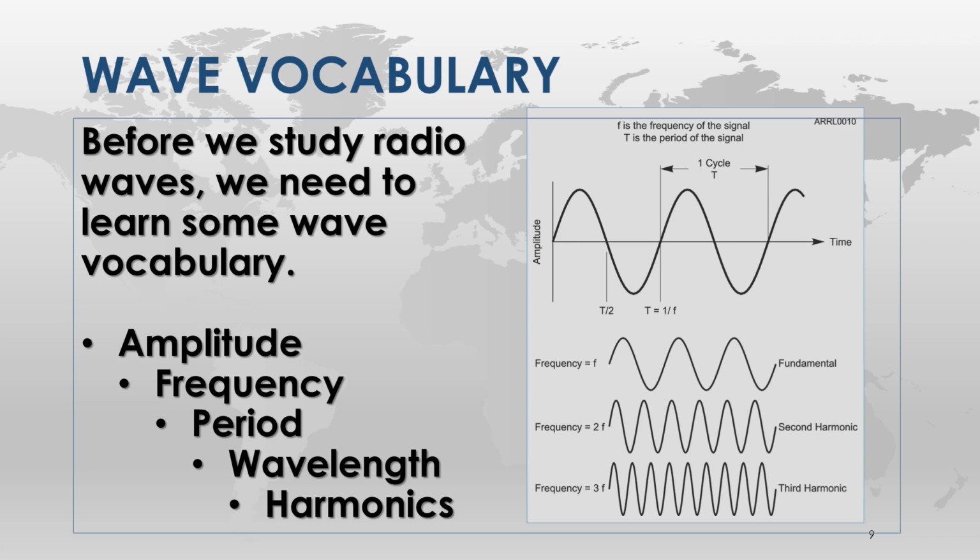Bruce, why do we care? What does it do? So when I put up a 40 meter, a 7 megahertz, dipole antenna, I can also use it on the 21 megahertz band. So you can make a multiple band antenna by choosing the right length for the antenna.